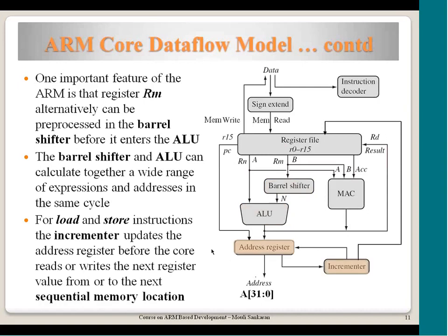And for load store, as I mentioned, in the memory there are non-sequential accesses and sequential accesses. Sequential access means that in the sequential access cycle, multiple address data locations are either read or written in the memory by one single instruction.